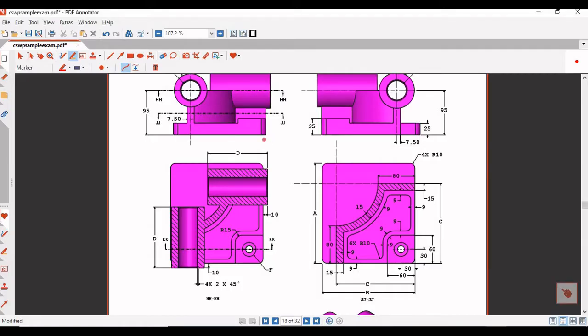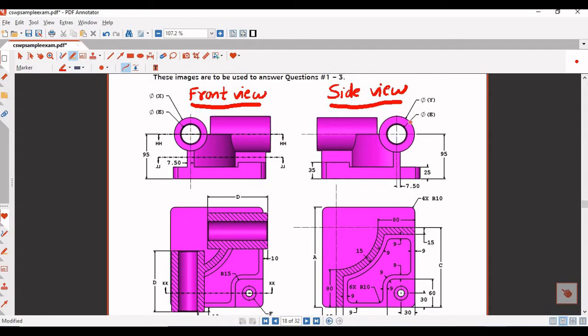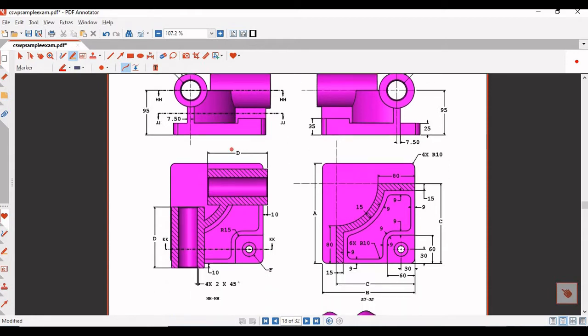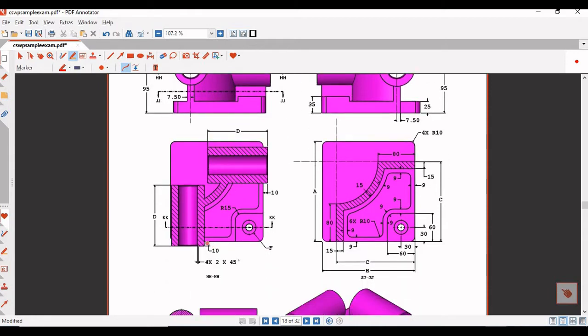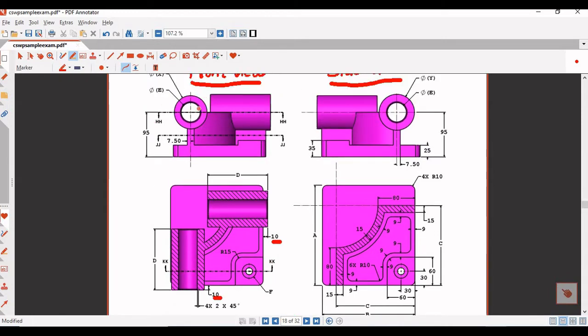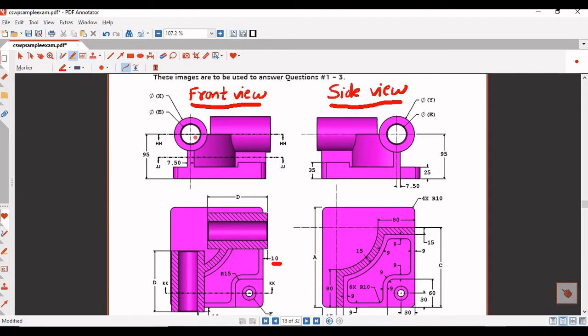Now what I will do, I'll create this cylinder that you see here. One thing to note is they are basically made at an offset distance of 10 mm, both the cylinders. And I will only create the outer cylinder first, not the inner cylinder, inner hole that you see. There is a reason for that. I will get back to you later on.